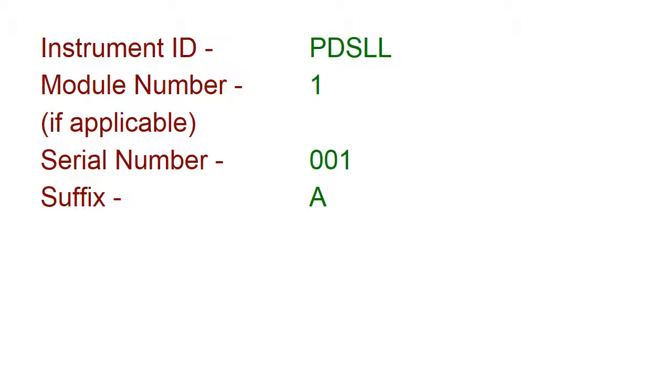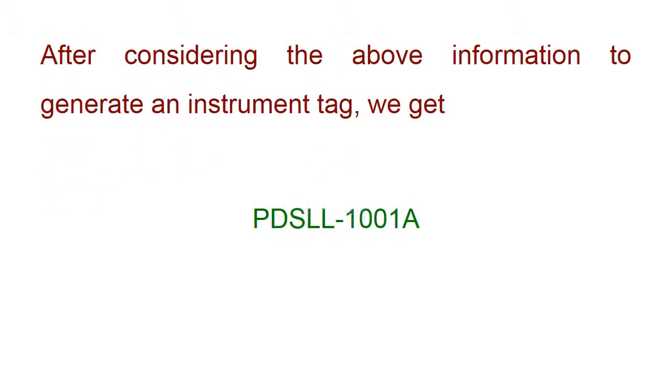Instrument ID, PDSLL, module number, if applicable, 1, serial number, 001, suffix. After considering the above information to generate an instrument tag, we get PDSLL 1001.